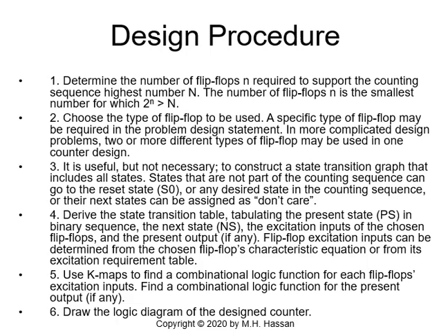Once we have all these data, we use K-maps to find the combinational logic function for each flip-flop excitation input, find a combinational logic function for the present output, if any, and draw the logic diagram design counter.